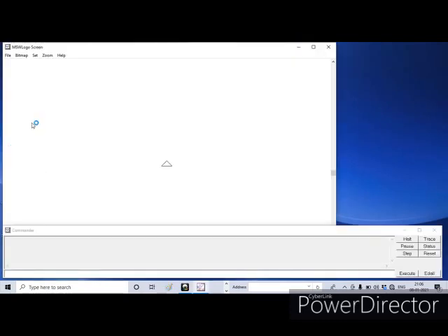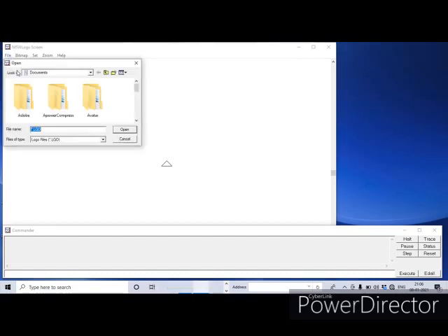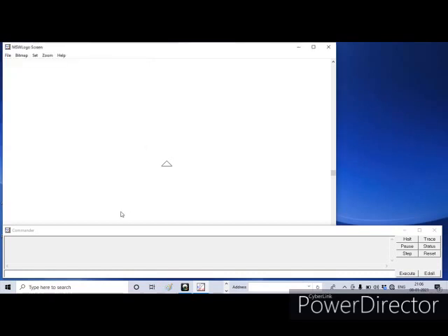After that, if we want to call that procedure, first we have to load the procedure, right? For that, click on the File menu, click on Load, and choose the file name. Select my hut 1, click on Open. Now we have loaded the procedure. And next we have to call the procedure. For that, we have to type the name, my hut 1.